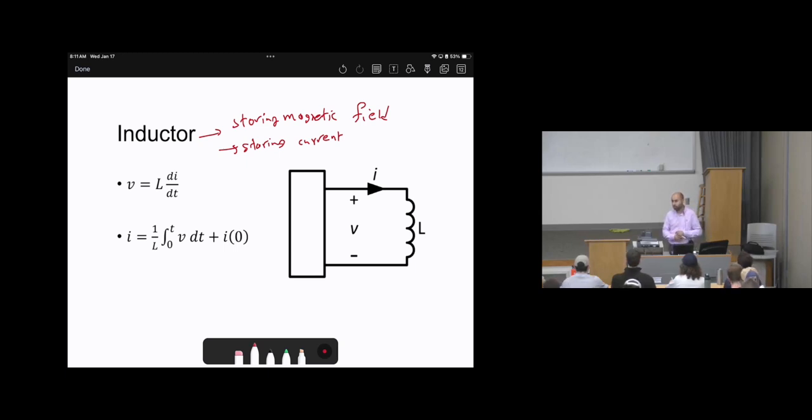So what they need to do is basically earthing. They will make the energy inside the transformer discharge to the ground. That's something we call earthing. So first, disconnect the power, isolating the components from the utility power, then earthing, so we can make sure we have a safe testing environment. One of the incidents, when I was working with a power company, was that the maintenance engineer actually forgot to do the earthing.